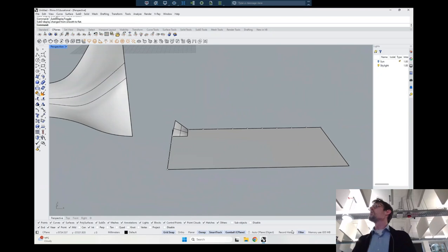It's called flow along surface, or flow along surf, SRF, because Rhino knows you don't have time. So, flow along. Oh, you've got to type all those out. But surf, that's a small one. Record history is super cool.